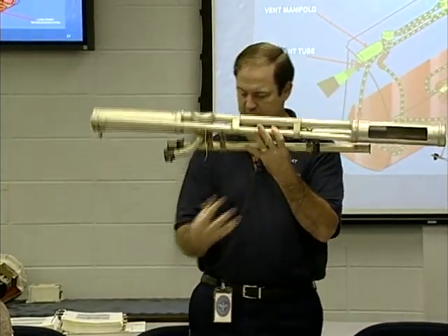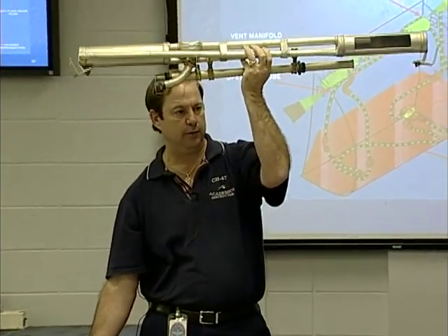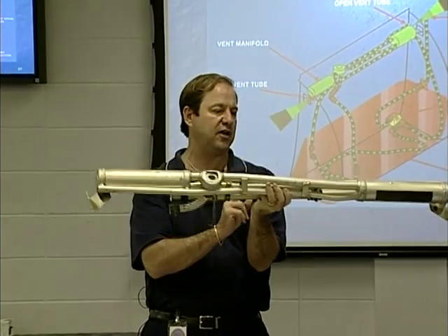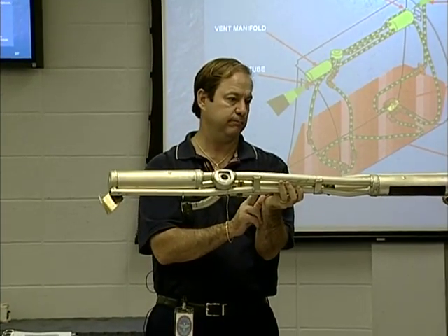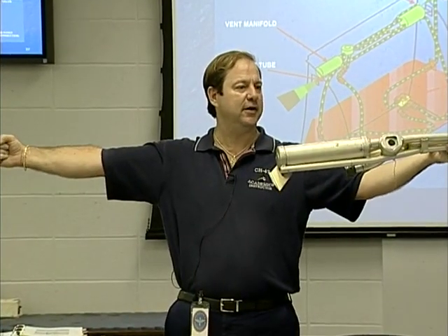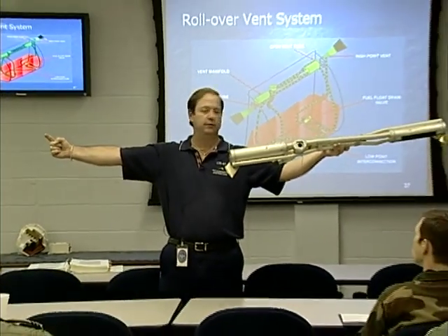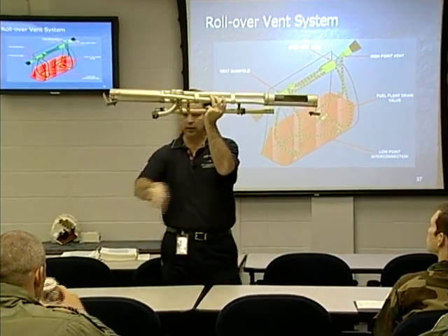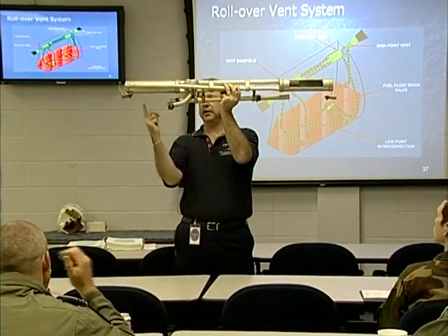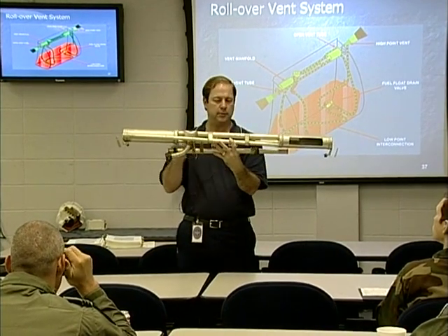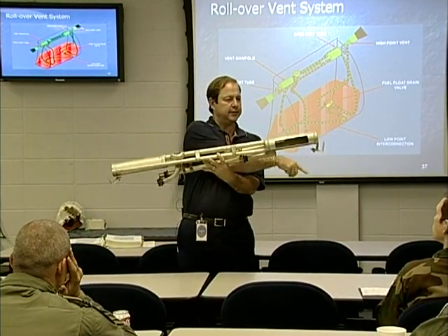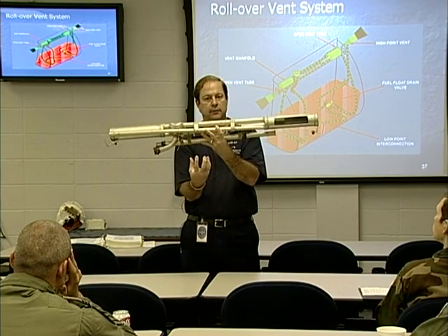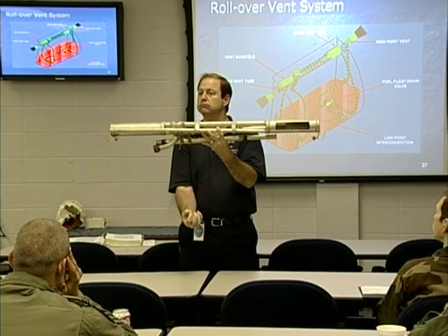But what happens is, because the vent's way down here, and based on which tank you have, this is an aux tank one, which means the main tank one is even bigger. Agreed? But all the tanks have them. And then based on the lines running up to here, it's going to allow air to come in and then get vented into the tank at the top and take the place of the fuel as we're sucking it out. Good?